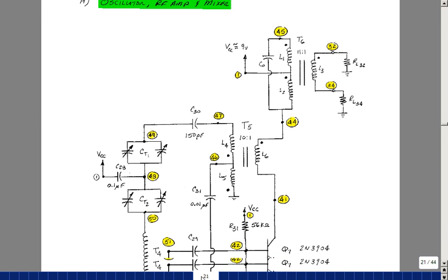I'd like to explain a little bit of how the oscillator is creating these types of results. Suppose that when we turn on the radio, we create a transient response. This C and L resonant circuit, because we've created a very high resistance through this path back to ground with the tapped L equivalent circuit, has a very high Q. So if you do have a transient response, you're going to ring at the frequency of the resonant LC combination, and that was, with the values here, about 1.08 megahertz.